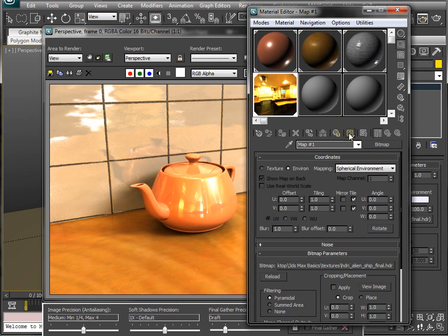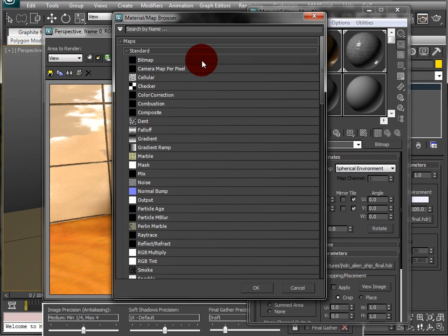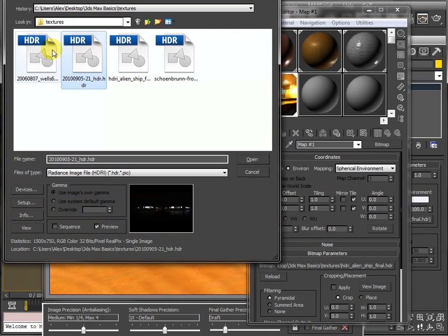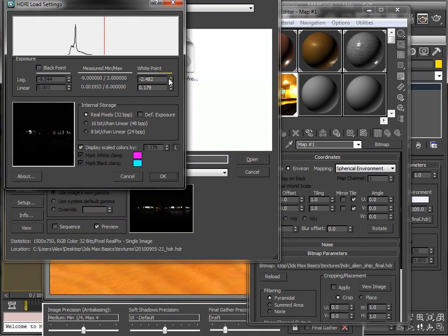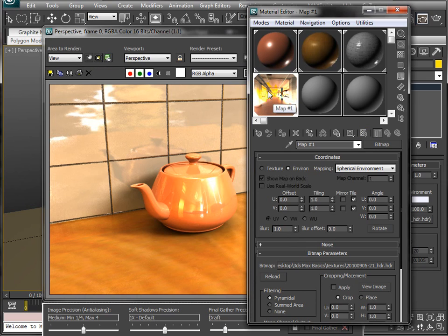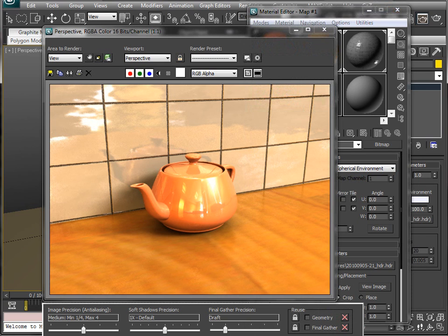If you're not sure how much influence it has, let's change that texture. I'm going to select this one here. It looks very dark there, but we'll find a good balance, so I'm going to drag that down. Again, I like going just in front of this nice high peak here. Click OK, and you can see that it looks like the inside of a warehouse, basically. One thing to watch when you're replacing the texture: sometimes it resets to screen, so you need to put it back to spherical environment, or you'll get some crazy results when you render. So with that in place, let's re-render.